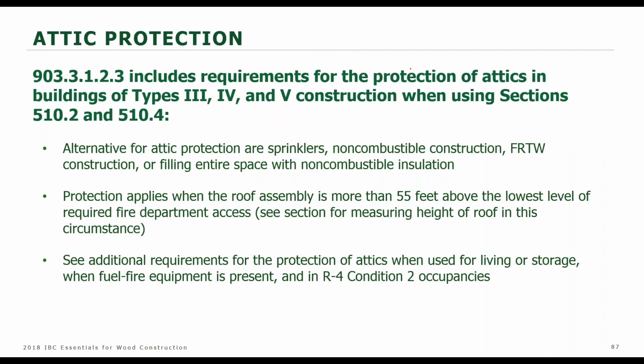New to the special occupancy provisions for the pedestal or podium buildings that I've been talking about here are some new height restrictions for what you have to do with the attic. So if you are over 55 feet above the lowest level of fire department access with a podium building, there's new provisions as of 2018 in 903.3.1.2.3 for protecting that attic with sprinklers.